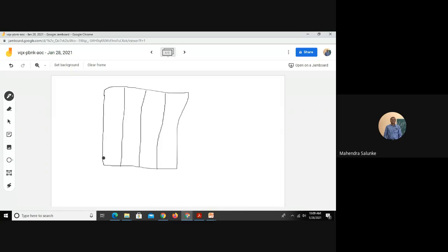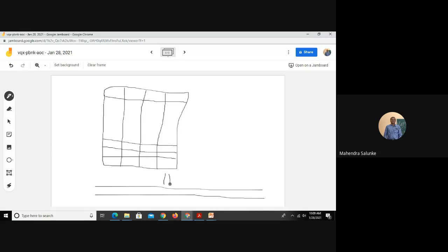So here if you see, these are the memory locations, right? This is how the memory chip is seen from the processor side. And here is our data bus, which is a 32-bit data bus, and the lower data lines are connected to this bank.